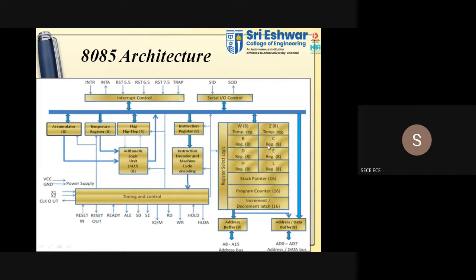Registers are used to hold information, a small size of information which is required for the ALU to process. In the arithmetic logic unit, what will we do? We are going to do some computations: logic functions like and, or, not, addition, subtraction, all done using this arithmetic and logic unit. So the data for this ALU will be given from these registers. A small amount of data will be stored over there in the register.